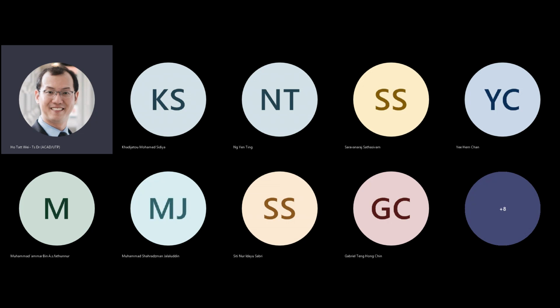In digital logic, I would say almost all our circuits have this form. You have flip-flops and you have what we call combinational logic. This combinational logic is feeding the next state into the D flip-flop, and the D flip-flop is recognizing that state.